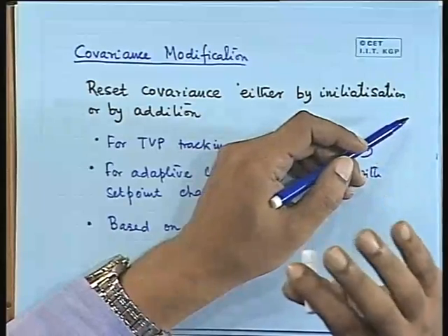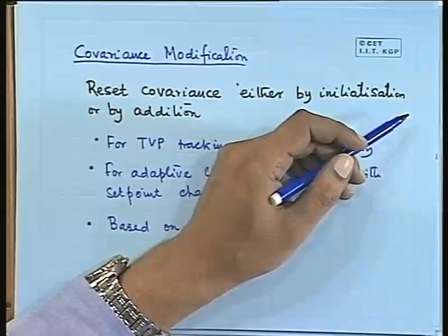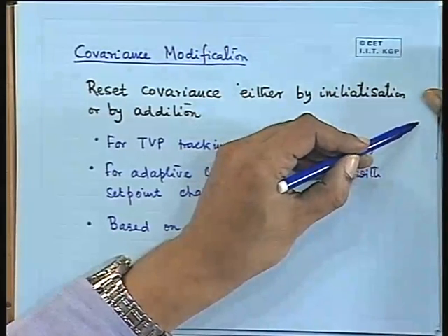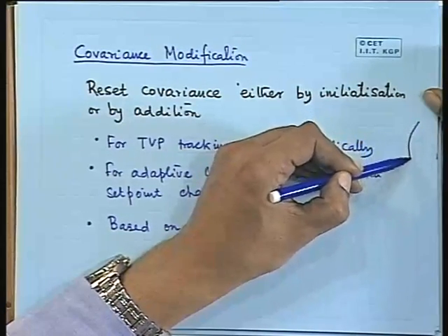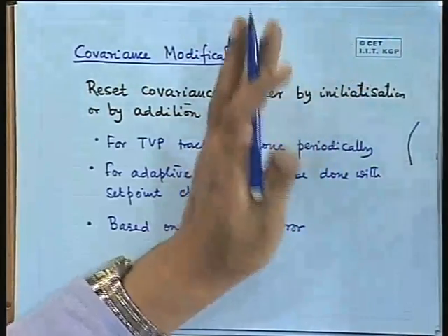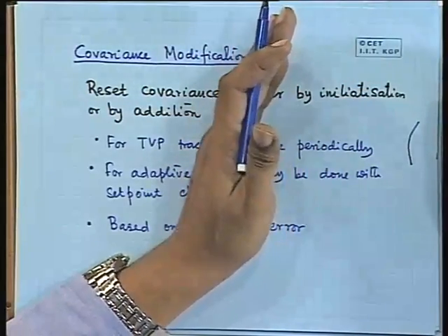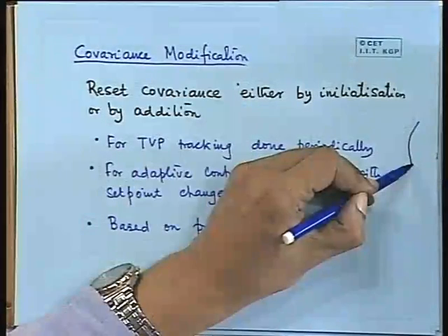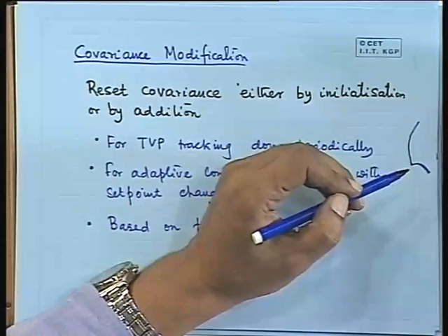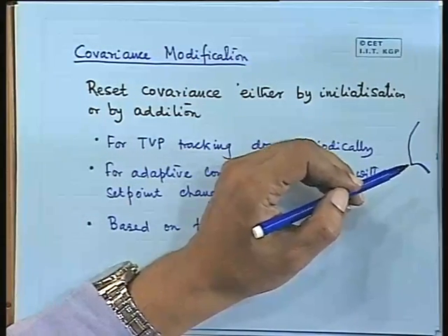So at each of those points the linear model changes. So suppose you are running an online estimator. What you are going to have is that the parameters have converged and your covariance has died. It will die. Now suddenly the operator has changed his operating point. Now the model does not fit.